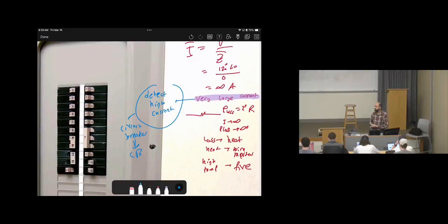However, we sometimes have problems with circuit breakers. It might not trip. That's why sometimes we hear about fires. So there's a problem that we don't like. We call it circuit breaker failure. A circuit breaker, again, is basically a mechanical switch. It will be turned on and off, and sometimes it can get stuck in the middle. It's rare, but it can happen. So with this type of problem, if there is circuit breaker failure, we are in danger.